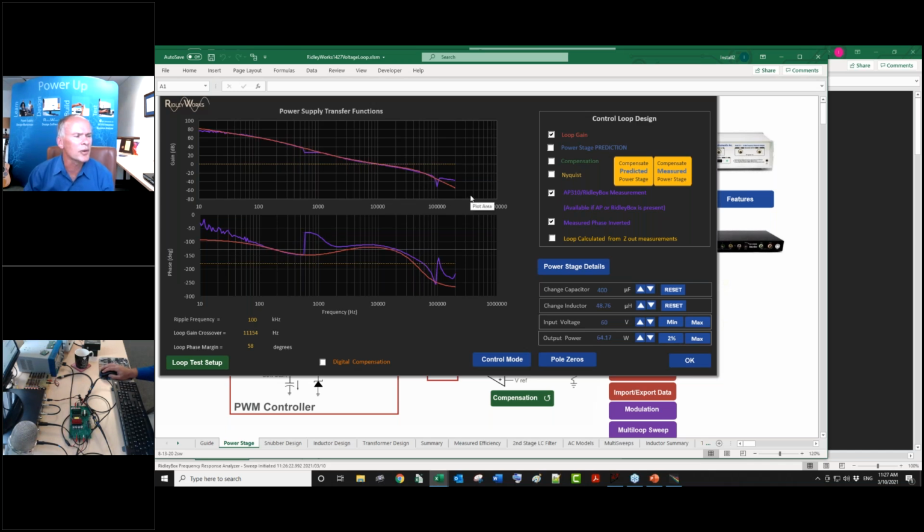Okay, somebody's asked the question, what do I think of the argument put forward? The Bode plot doesn't show you stability in non-minimum phase systems. I think somebody's reaching to write a paper or sell a product, quite honestly. Every converter is a non-minimum phase system. It's got right half plane zeros in the current loop flyback system. It just works, and everybody's used it.